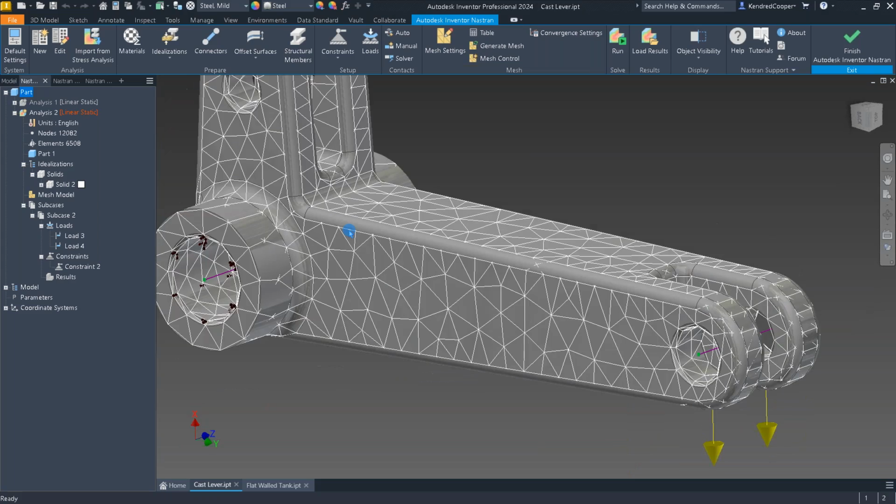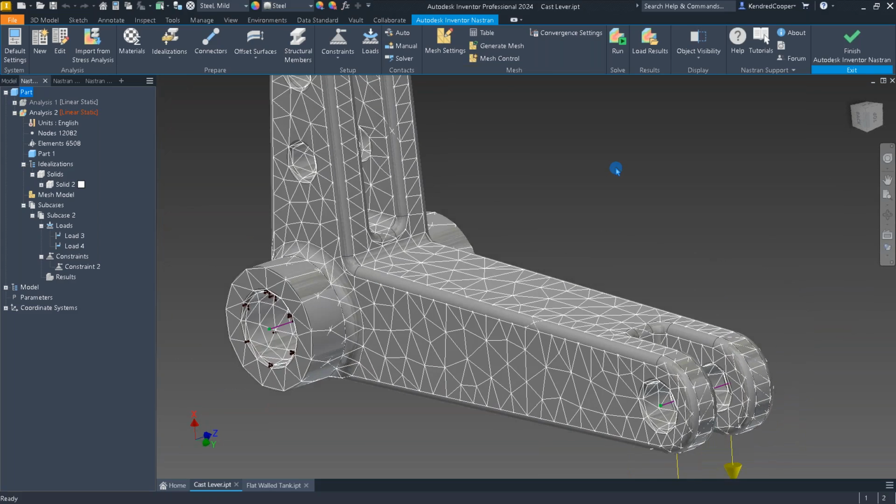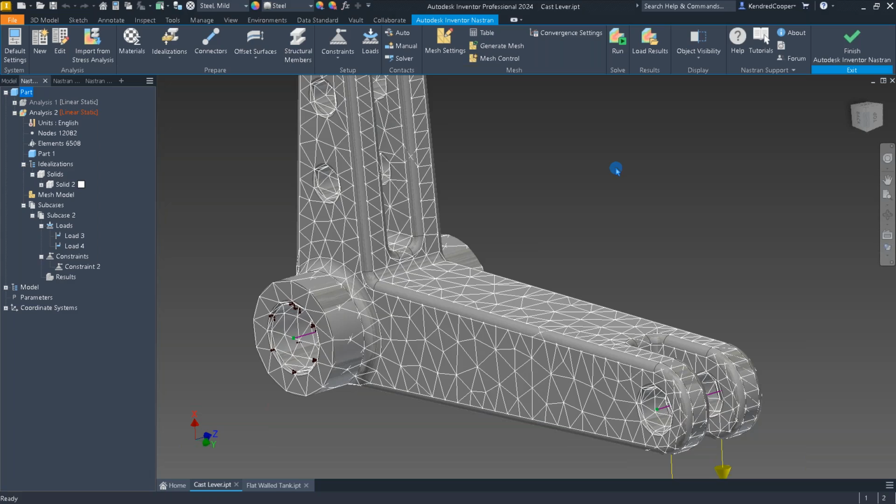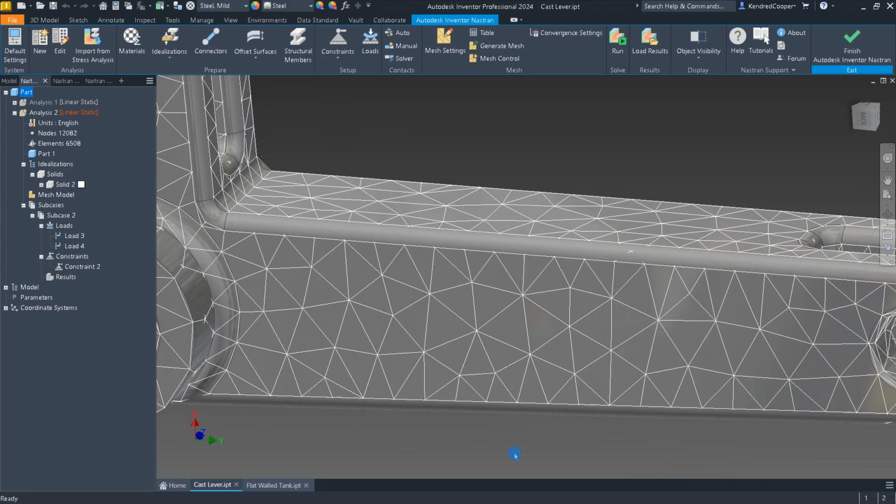But what you want to look for doesn't really come up too much with a native Inventor model. But if you're working on something that's an imported step file or coming from another CAD format, it can happen. You can have in the middle of nowhere a sudden concentration of the mesh changing size and changing quantity.